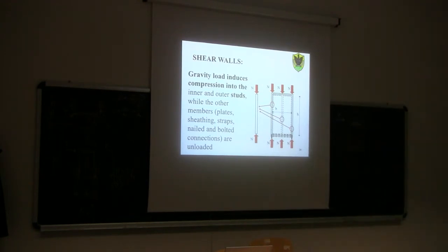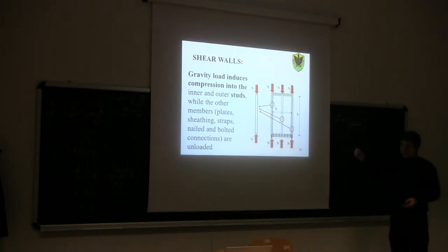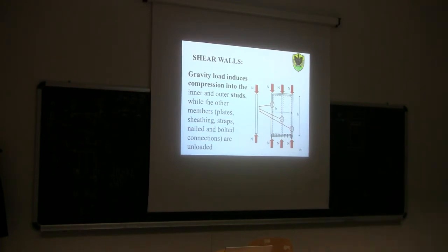What are sigma and tau? What kind of forces are they? Tau are tangential forces. Strictly speaking, they are concentrated forces in the nail, so each nail is transferring a shear. But since there are several nails, we can also consider what we call a kind of shear stress per unit of length. So we could say, okay, here I would have a force.